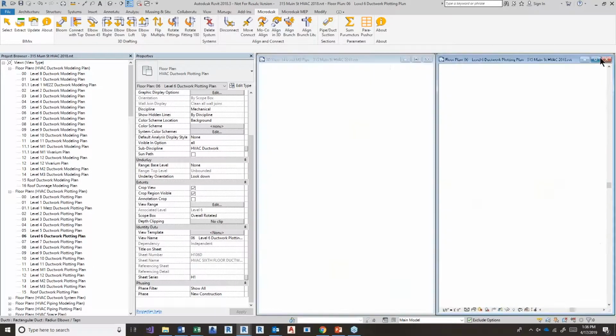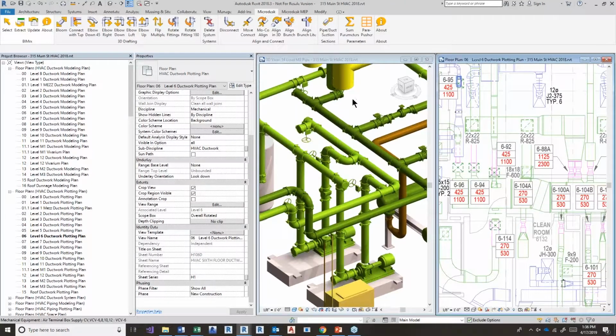Let's try something else real quick, and this will just be another simple example. I mentioned there's a lot of cases where we might have senior leadership who is not fluent in the Revit software, but nevertheless needs information to perform their own calculations or their own assessment of the project status. So we can use BIMrx to export information. And in the example I gave earlier, we might want to calculate a volume inside of a pipe system. And I know Revit does that natively if everything is connected properly. But we know in practice that that's not always the case.